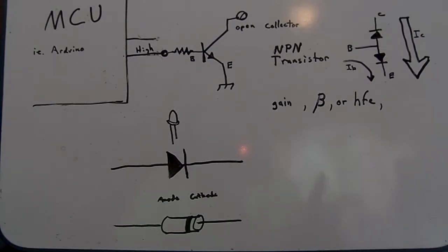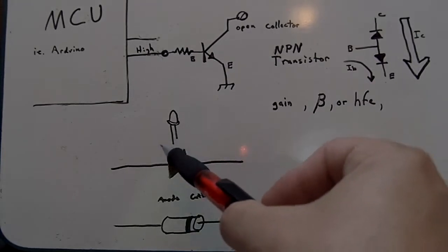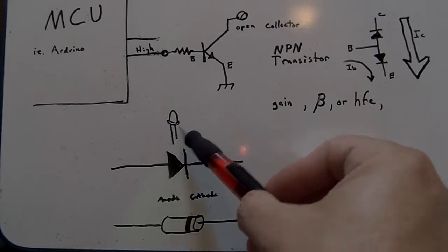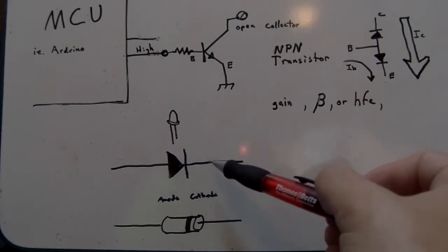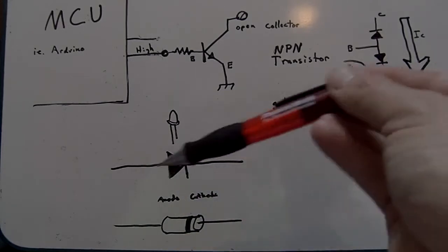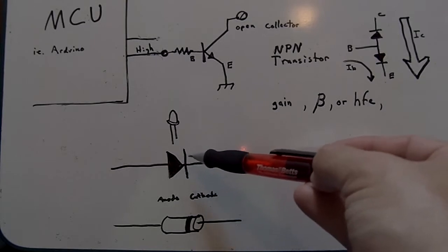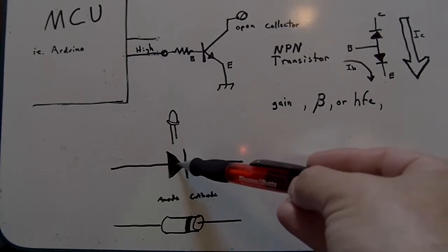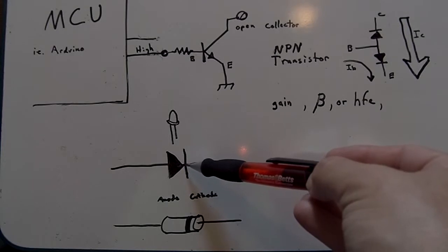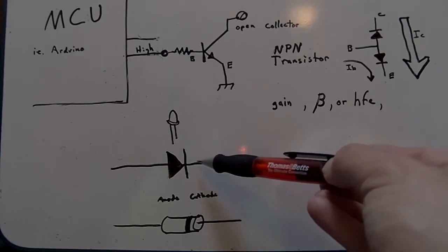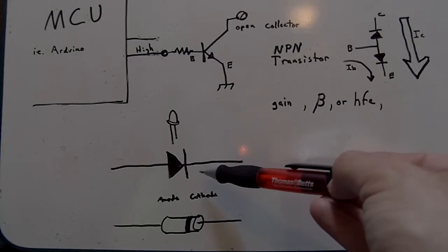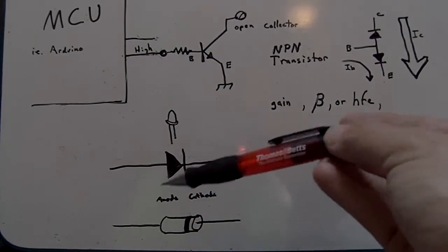So an LED is a one-way device. A diode is a one-way device. In the forward direction, you'll drop a little voltage, and an LED drops a little more and produces light. This just produces a little bit of heat, where it's 0.6 that it notches out. Now, on the backwards flow, you've got a peak inverse voltage rating in a diode. A typical 4001 might be, I think, a 50 volt, and then the 4002 I think is 100 volts, and then they go on by hundreds from there, or something like that. So you get as much reverse rating as you need.